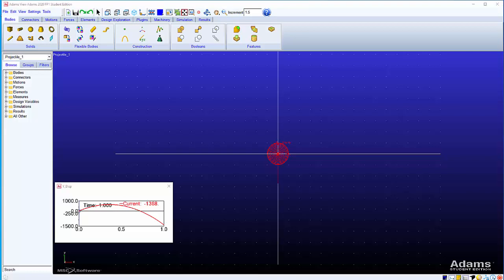So instead of saving Adams as a database, we can export Adams as a text file, and this text file will be a very small text file. At the same time, you can share it with other colleagues. Also, when you load it, most of the time it will be very easy to load. This file is usually called an Adams command file. So the way we do this,